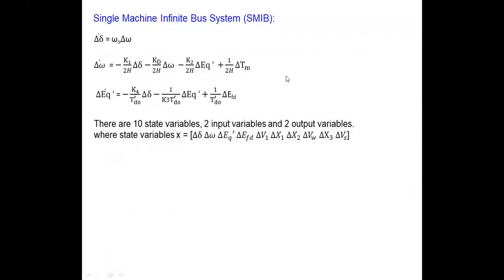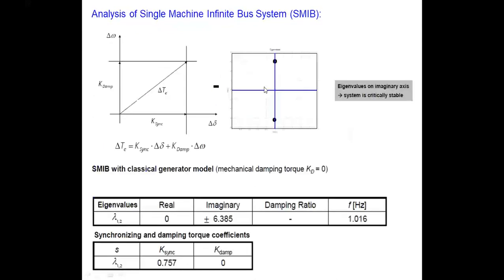And then, yeah, here I have listed down the complete equations. So you have all these state variables. This omega naught you can consider your reference, so for 50 hertz it is 314 radian per second, and for 60 hertz it will be 377 radian per second. So it is this one, right? So maybe